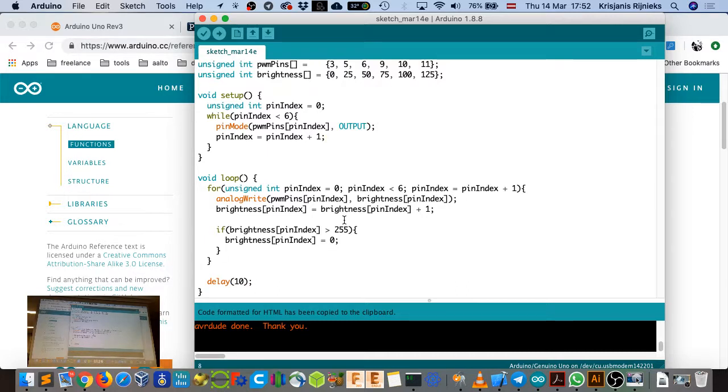What is the resistor? The resistor is to protect the LED from pulling too much current and eventually burning out. Because LEDs are usually rated for 25 to 30 milliamps, and the pins of Arduino can provide 40. Sometimes too much current is flowing through the LED, and then it burns out. But if you put a resistor in the chain, that means that it takes part of the load.